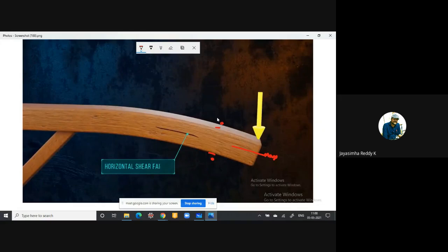While solving bending stress, we have taken pure bending, and there is an absence of shear force. Assuming that shear force was not applied at all and there is only pure bending, we have taken that element which is undergoing pure bending and we have solved simple bending theory. Whereas here we have seen shear stress. So why is it maximum at the origin?